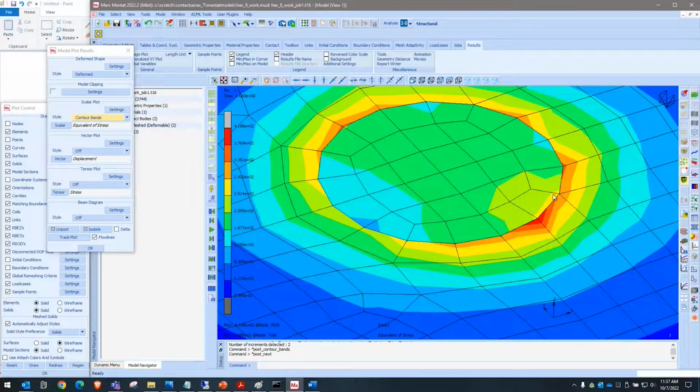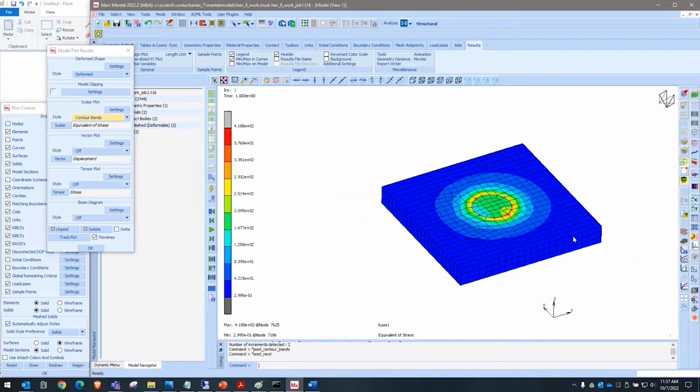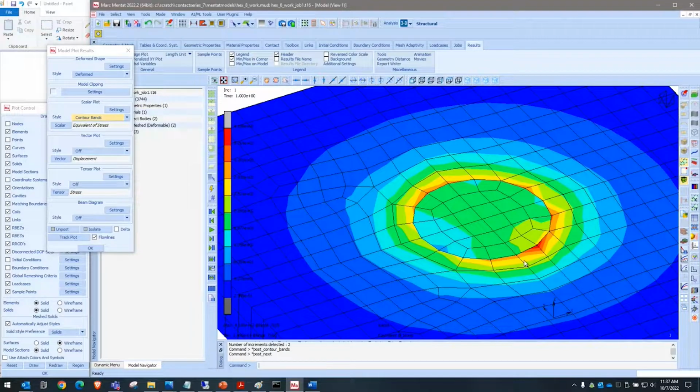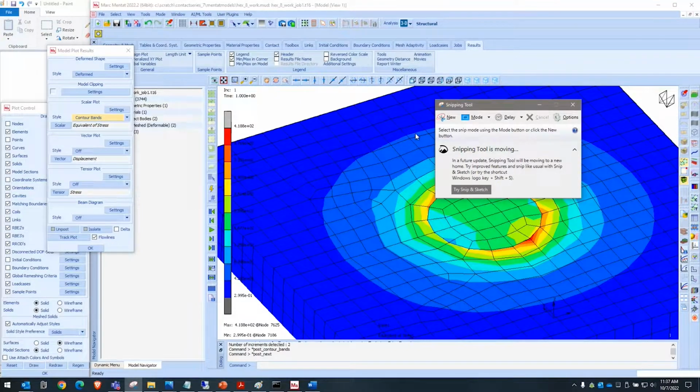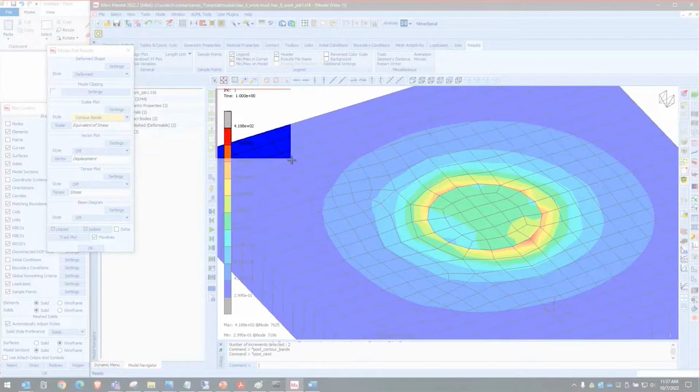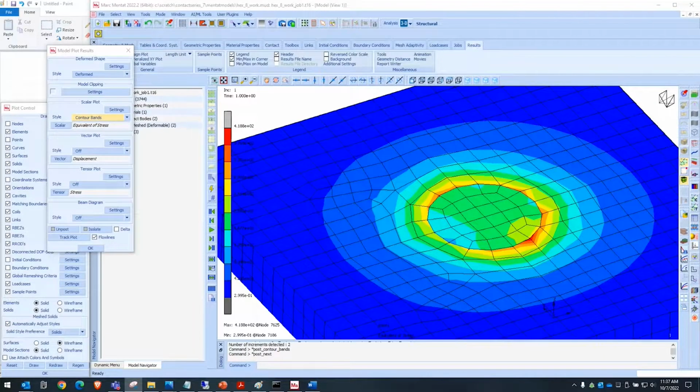So as I go in the circumference, I expect to see not necessarily constant stress, because that would require this to be a circular section so that it's symmetrical, but still some kind of an oscillation, at least with very minor changes from the center to that. So those points should be the same, and this one maybe a bit higher or lower depending on how the structure behaves. So at least it's a reasonable first order answer, but it's definitely not great. Let's just take a snapshot of that number over there so that we've got a reference later on if we start tweaking the model.